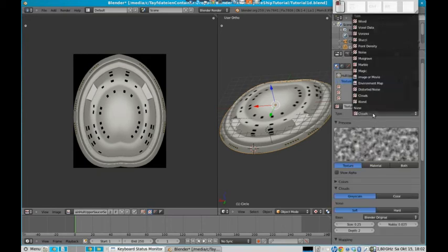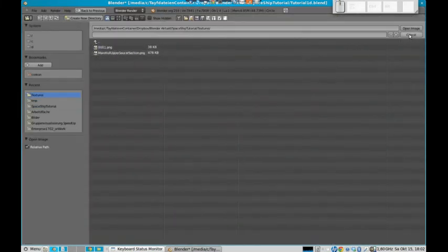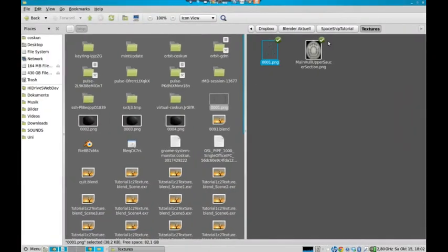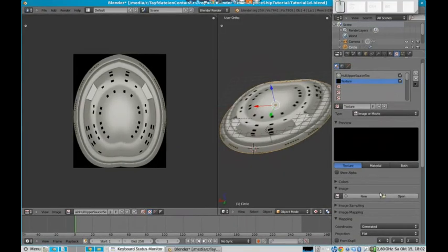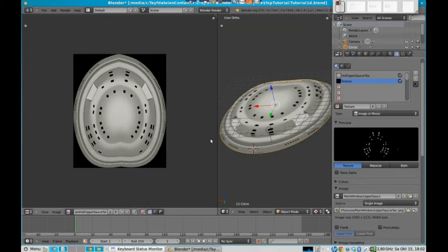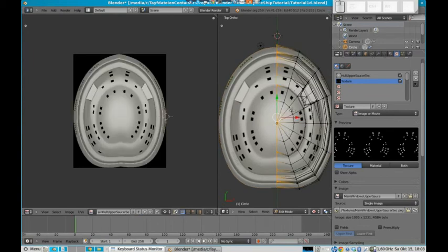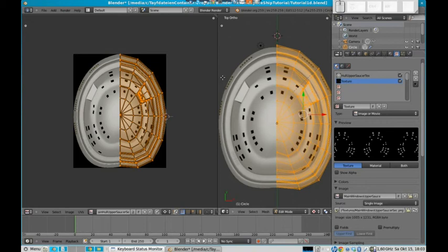We want another one now. This will be again an image one, but this time I of course should give it a good name. Main window, upper main window, upper saucer section. Back to Blender, open textures, saucer section. Yes, that's it. Let's select that here too. Main window. And since we already defined the UV coordinates for that, it should be already perfect.